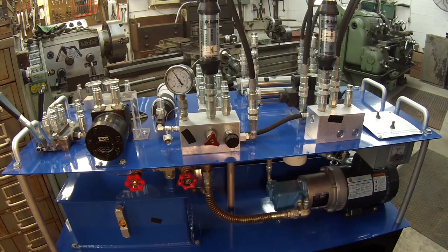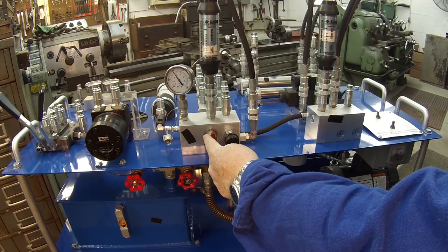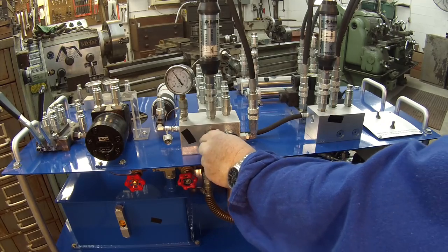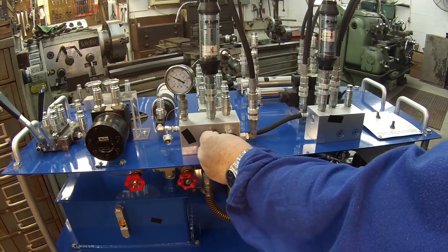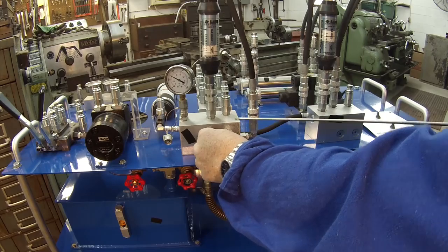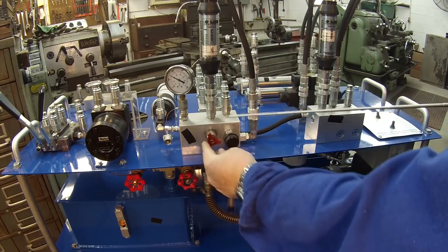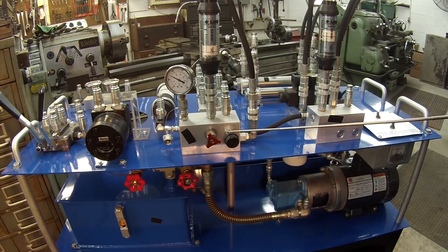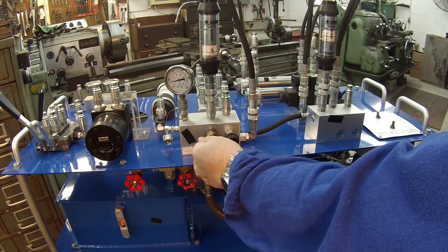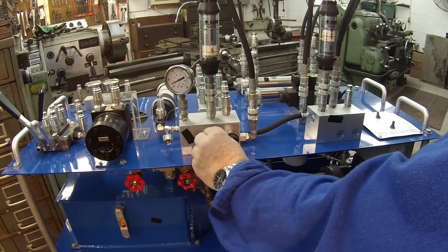Alright, so what I'm going to do is prove to you pumps don't pump pressure. I'm pumping 1.8 gallons per minute right here. So what I'm going to do is open this bypass valve and give it an easier path back to the tank. So what you'll see is, you see that pressure drop right there? That's because I'm giving it a free path back to the tank and it's not having to go over this relief valve right here. Okay? So as I open that up more and more, you see the pressure drops down.